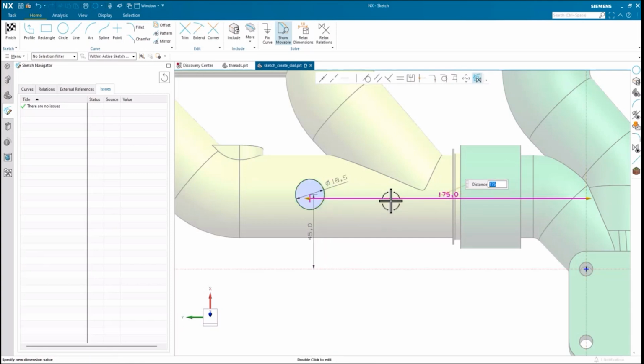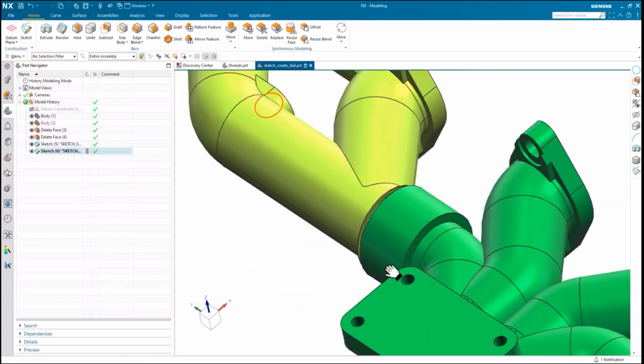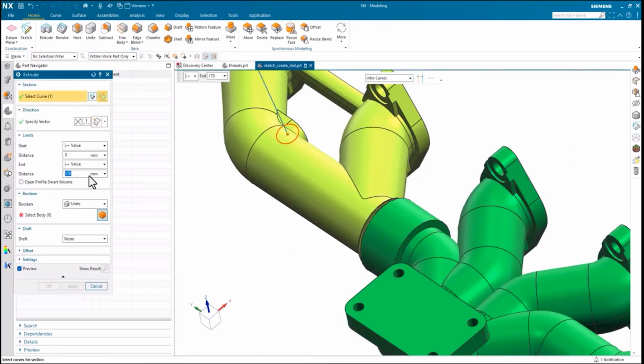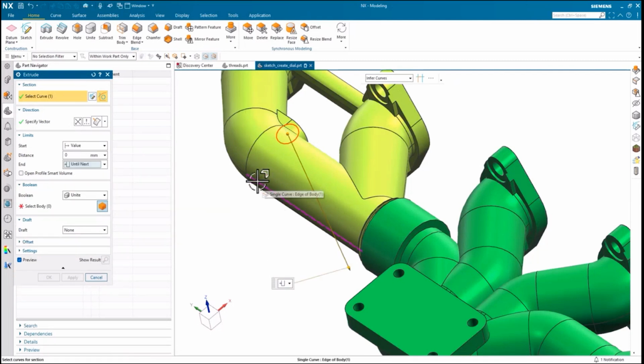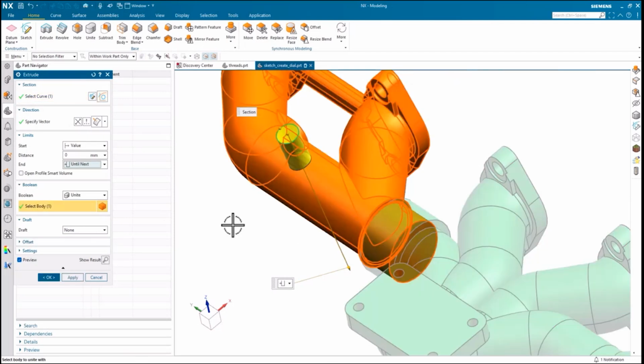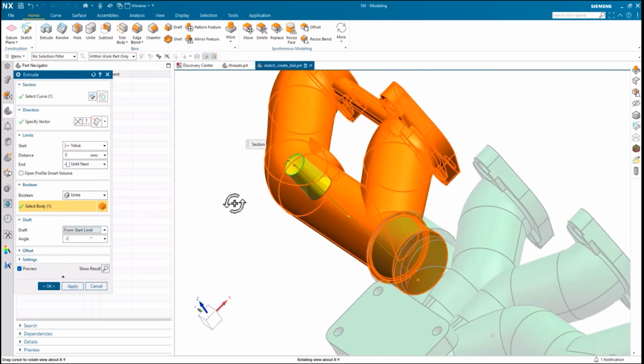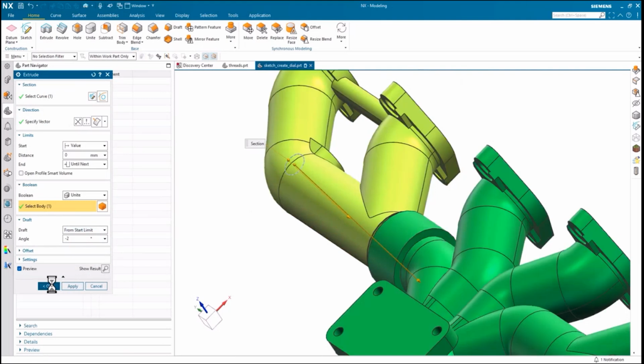And then, of course, finish it out, extrude it, and then begin our next few processes for creating either the boss or adding more geometry to our intake runner or exhaust runner. So here is a quick look into how you can use different extrusion functions. In this case, I'm using a unite function until next. So you can see that it actually perfectly goes right into that curve.